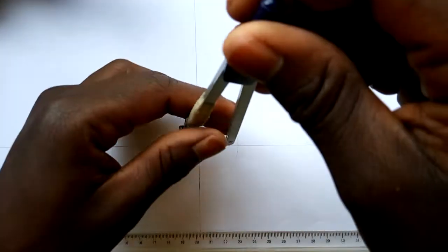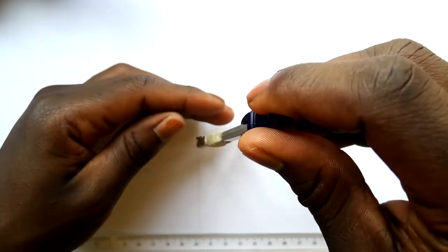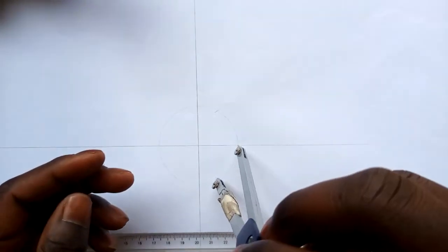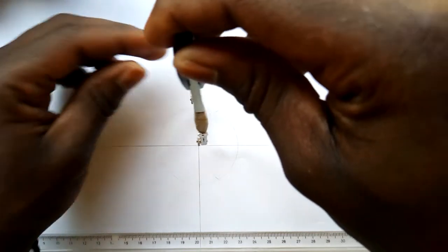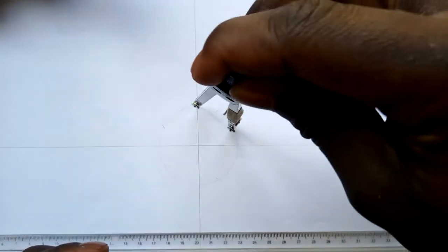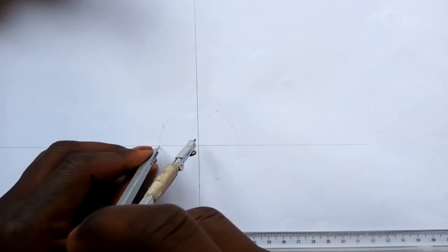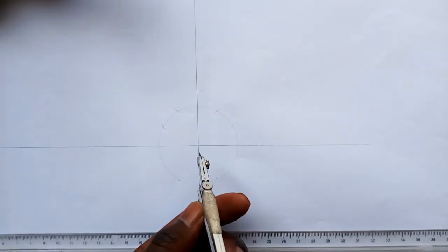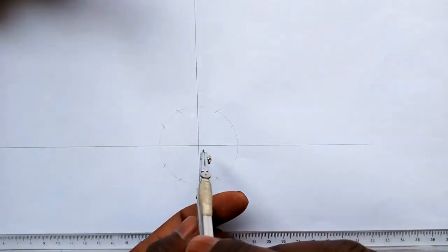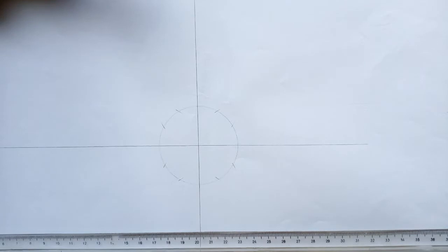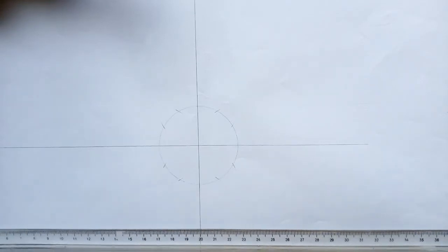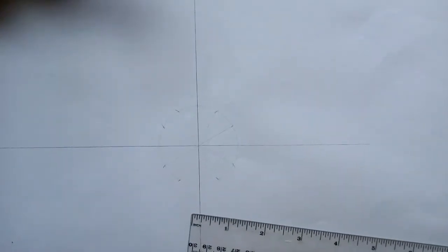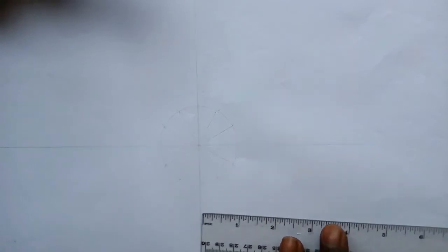Having drawn the circle, without changing the radius, I can do the divisions of the circle into 12 equal parts in advance. Stand there, come on the other side, strike an arc, come on the other side, strike an arc, go on to the last point, strike an arc. So my circle is divided into 12 equal parts. So the whole point is just to draw the object as it is.